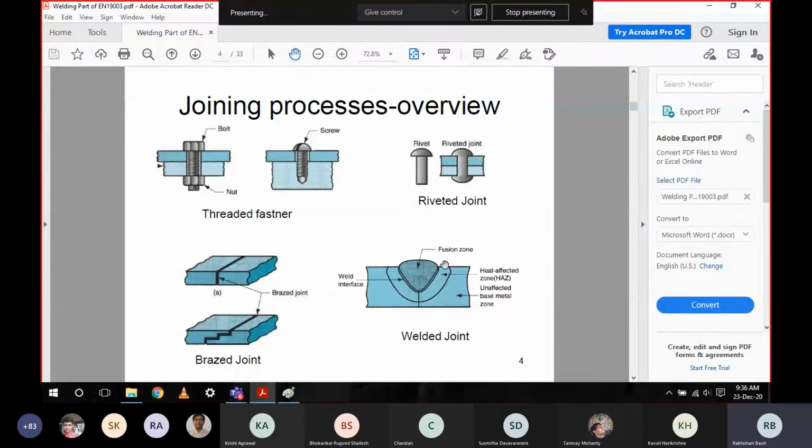And after that, in the base metal where heat penetrated, the heat affected zone, they will also have some cooling rates. So they have different kinds of grain structure or grain sizes. Now you can control this cooling rate to control the strength of the material or the weld.